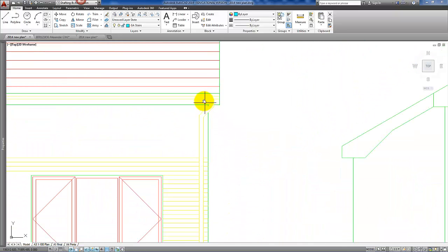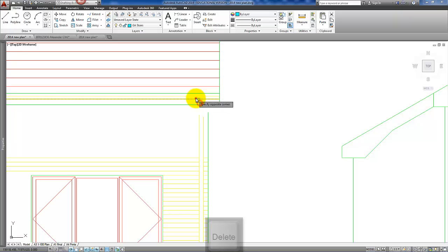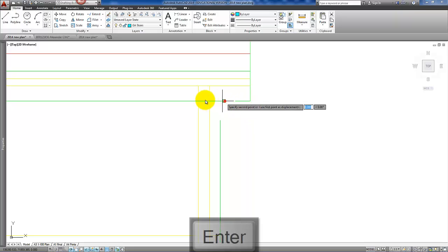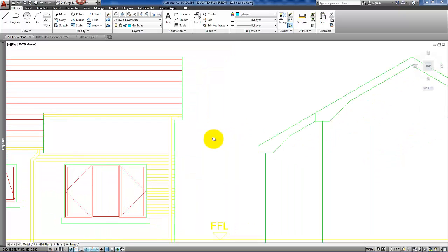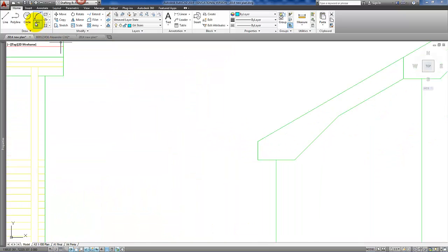And really the way those downpipes are, again, they should be carried straight up to the gutter like so, and we'll stretch that across there, and we'll extend that line up there. So it should be straight on the front and back elevation, but on the side elevation, really what you should be showing here is a semicircle.